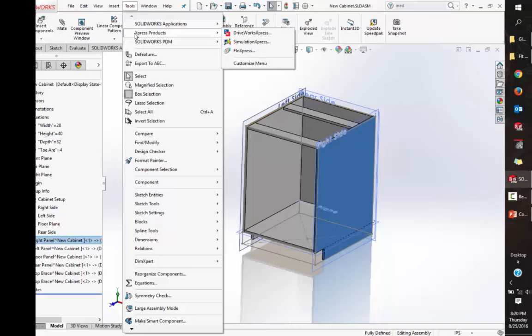The only downside that I found with the Express tool was that it would not rename the dimensions. So after a minute, 55 seconds, you had to do a slow double click on the drawing, because the part was actually named correctly, and you just had to update the file name of the drawing to match it. That was the downside. All right.